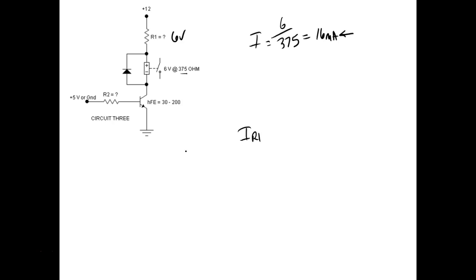So you'll run into this all the time because in electronics, usually we have standard power supplies. I mean, you have 12 volts, 24 volts, and you don't have somebody making a 3.3. Well, 3.3 is standard inside computers, but you don't have somebody making a 33.7853 power supply, right? So what you do is you get what you need, and then you compensate for it later on. I've seen Zeners in a circuit to set the voltage for different devices.